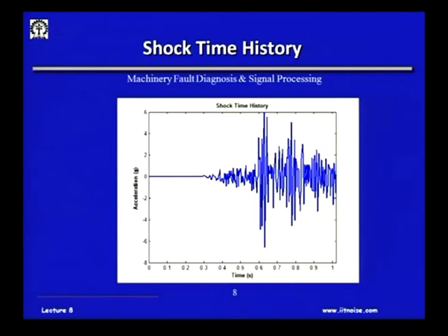This is just to give you another example. We are talking about the vibration isolation case. So, this is a typical case of a shock which occurs in a machine, and this is how it looks in the time domain, and these values are actually -6 to 6. These are values measured from an earthquake, and this is a very low level; I mean these levels could be 25 G. And this is what the time history of the shock wave looks like.